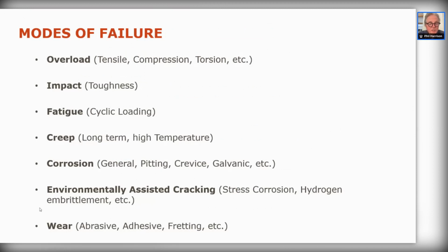We have fatigue life, which we're going to talk about a little bit more later, which is cyclic loading. Creep, which we've briefly covered, which can be long-term, can be high temperatures. Once again, it's just extension under load. Creep can happen at room temperatures, but it's a very, very long-term process on most engineering materials, except if you've got something, for example, like lead, which can creep very quickly at room temperature.